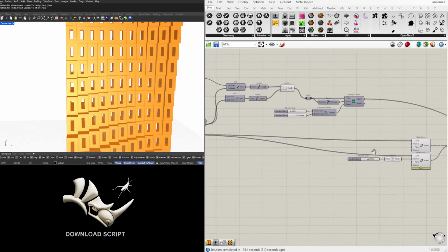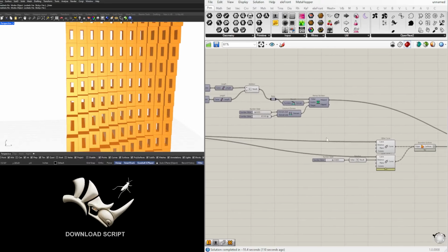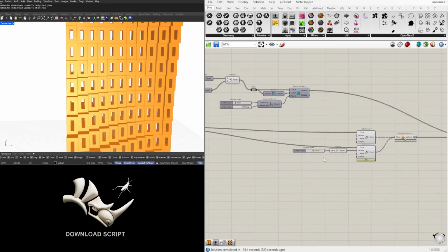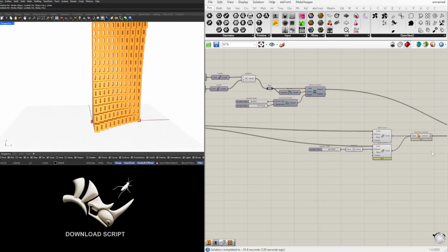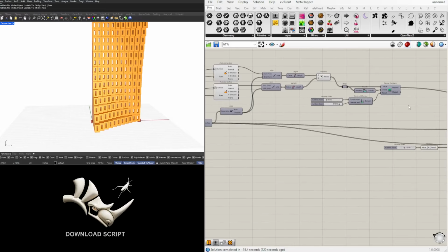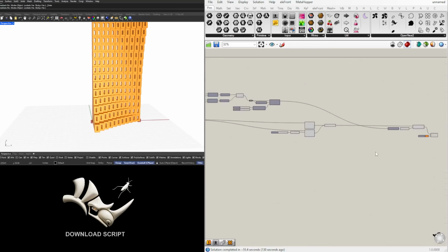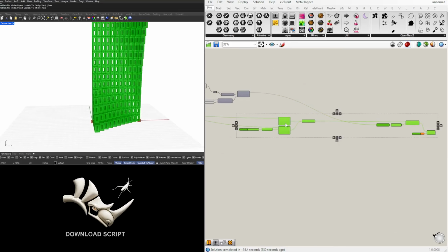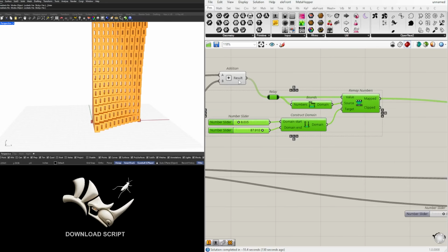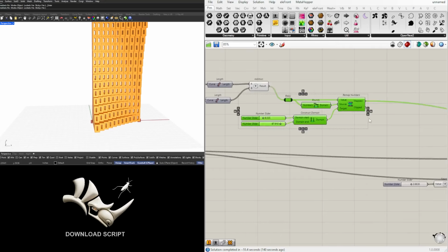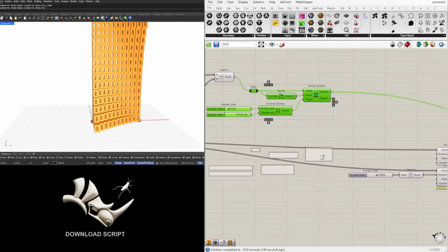So using a point attractor, we can create a minimum and maximum number to create some variation on the offsets. If you like them all being the same, that's fine. But here's what we can do is going to move this over here. Since we already have a set of numbers and a way to remap them, all we need to do is copy this.